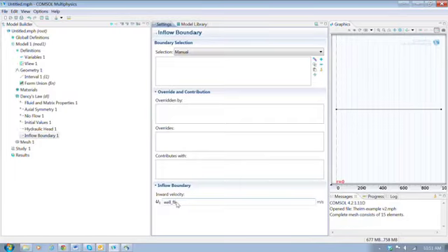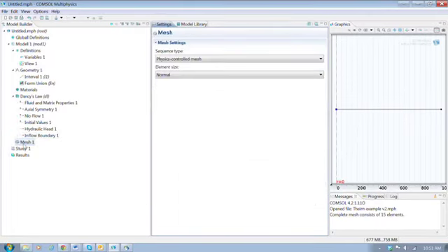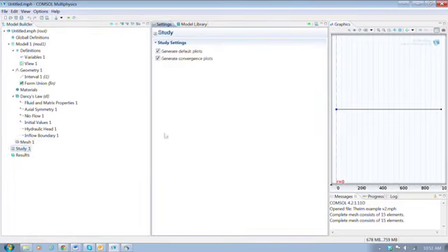And that is our boundary condition. We also have to select it here, so I'll pick that and press the plus, and so I have the numerical indicator of this boundary location set up. Okay, so the next step is the mesh, and in this case I'm just going to use the default mesh, and so it puts mesh points on there, and we'll go here to the study and it's ready to run.